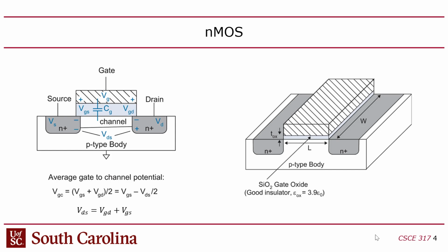Now what is the point of all this? Well, basically, when you look at the gate voltage, generally speaking, you look at VGS. When you evaluate the gate voltage on an NMOS, you're usually looking at VGS, or actually on a PMOS too. Either way, it's gate-source. That's not gate-channel, but gate-source. That's generally the voltage you're looking at to determine whether the transistor is on or off.